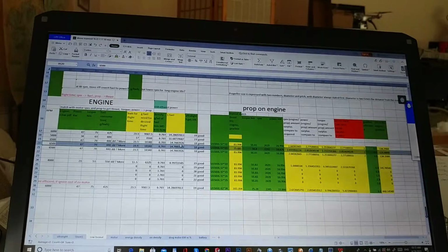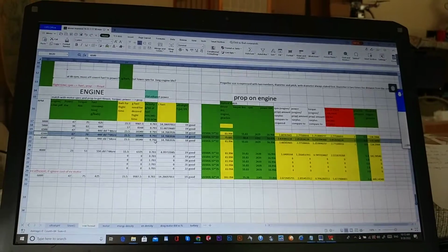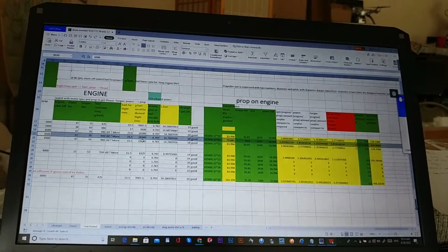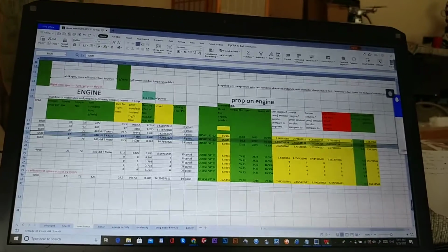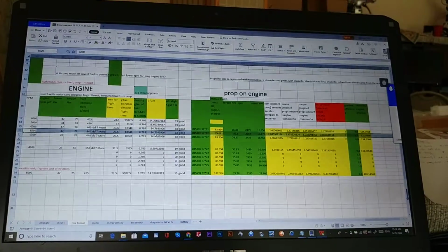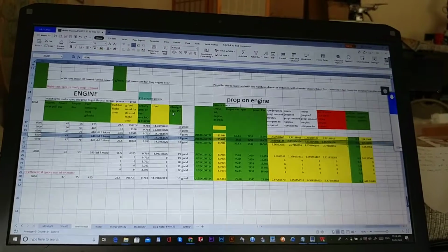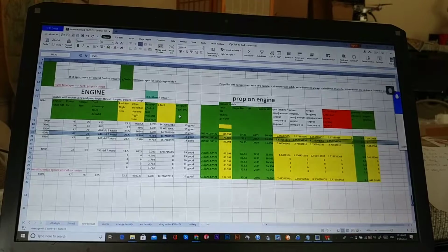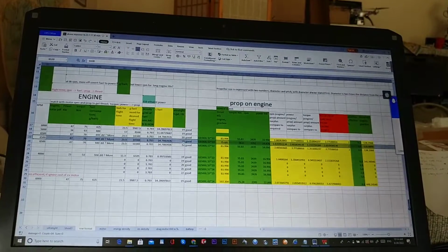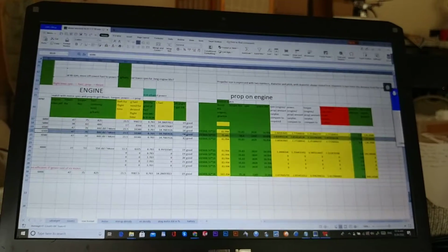And in turn, I calculate the weight, which is not much at all, and it's calculated into the total weight. So this is about 10 kilograms of fuel, which weighs nothing compared to the battery. And I make sure my gas tank is big enough. Those usually come with a 5-gallon tank, mostly 10. So 5 gallons is 19 liters, so I have enough. I only need 18 to achieve the flight time.